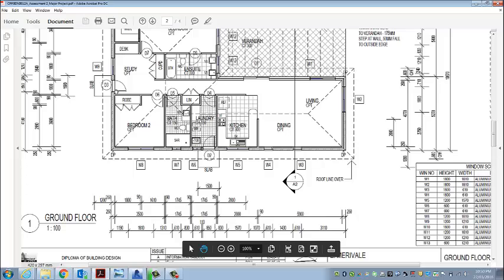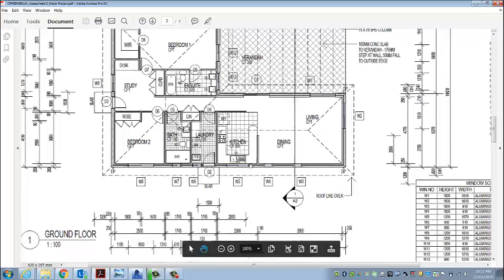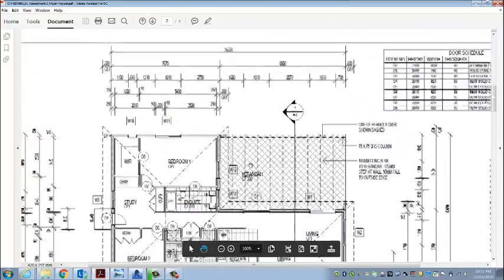It will start in the centre, so you can see that 1800 actually denotes the cupboards and then that wall, and then we move to the overall size of the walls of the room, and then we finish with the setouts from the external face here of the windows and the doors, all of the openings in this external wall, and then finally it would be the overall, but that would appear up here.